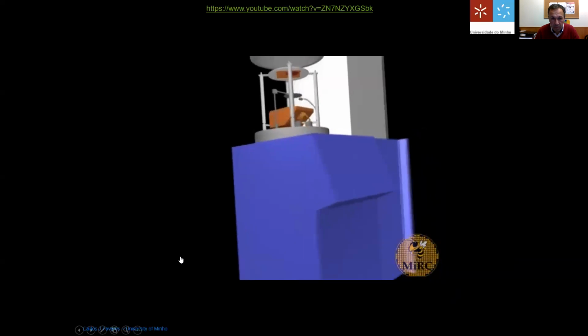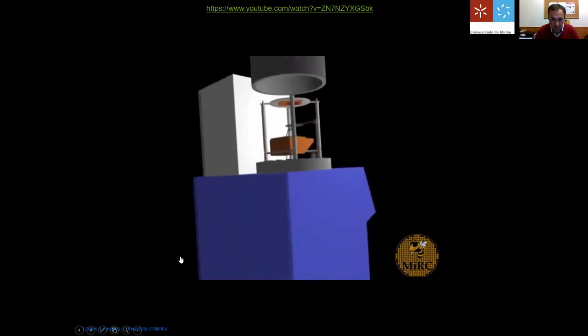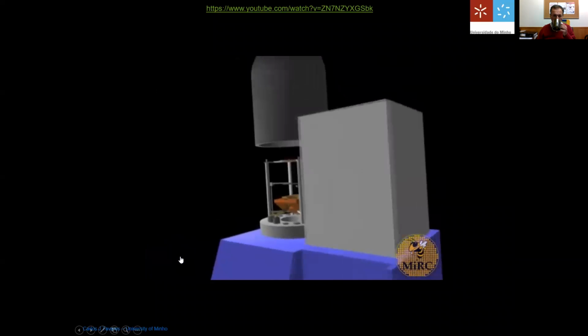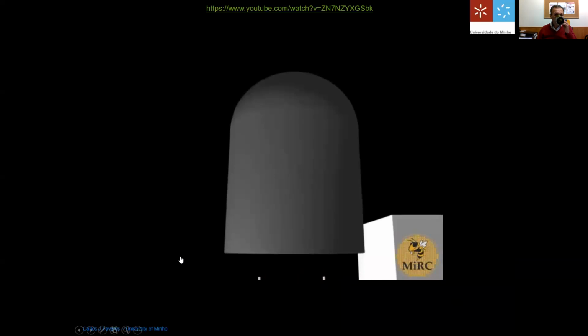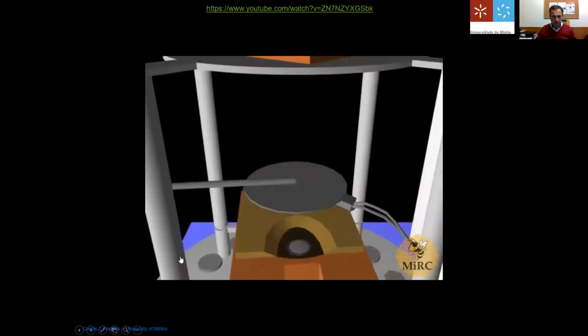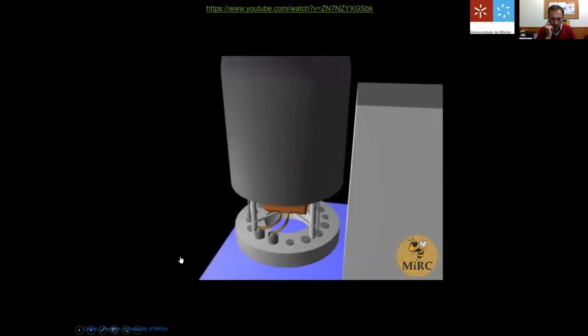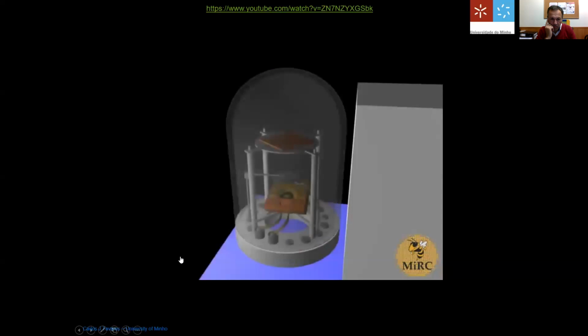An electron beam evaporator, a type of physical vapor deposition tool, is used to coat one side of a sample with various metals. Commonly used metals on this machine include aluminum, platinum, gold, chromium, nickel, copper. Once a sample has been loaded, the chamber will be closed. The chamber is then pumped down to a very low pressure.